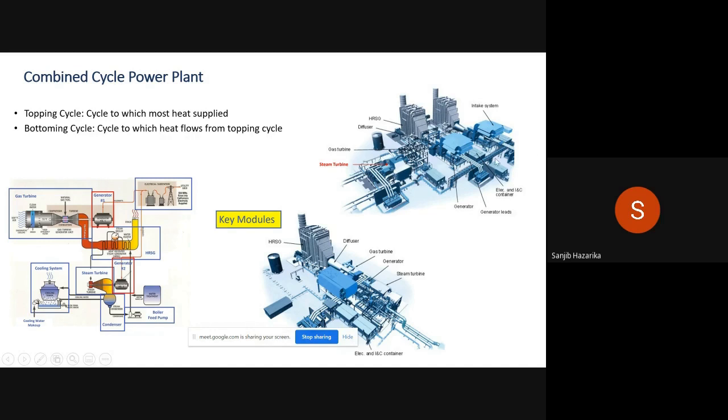So it's two gas turbines and one steam turbine, a 2-on-1 configuration. This is basically the system of a combined cycle plant. We may have 3 steam generators as well as maybe 2 steam turbines. That depends on the customer requirement and how we optimize the combined cycle power plant to get the best overall performance in that particular scenario.